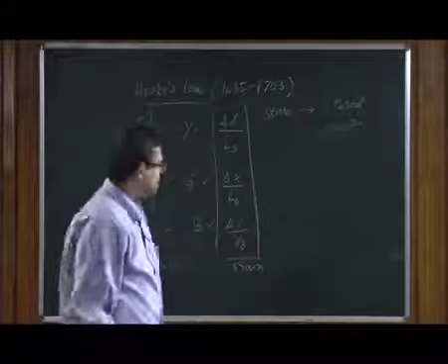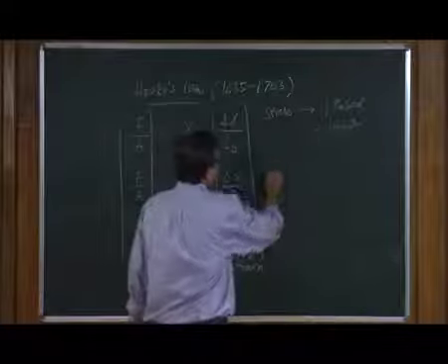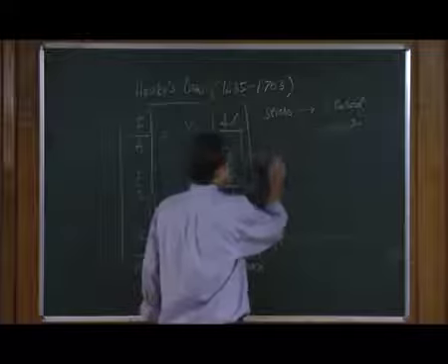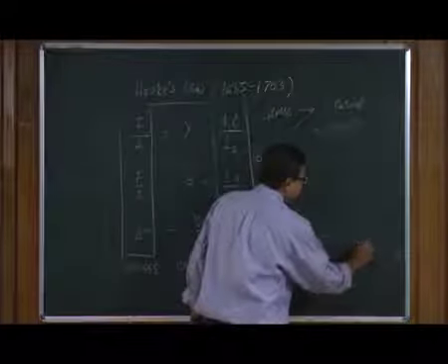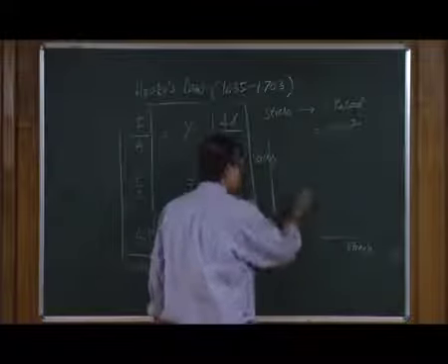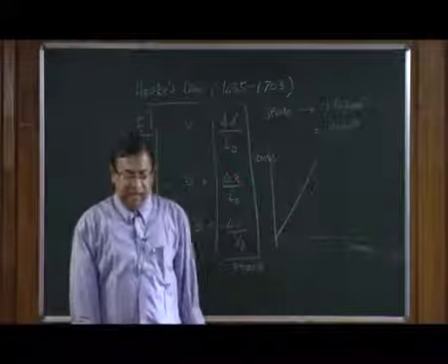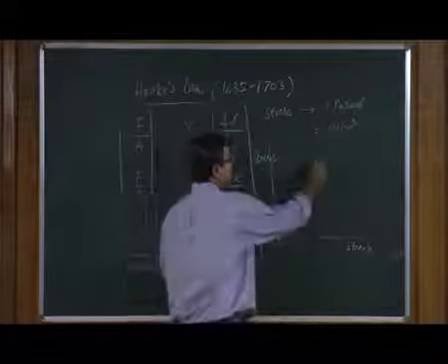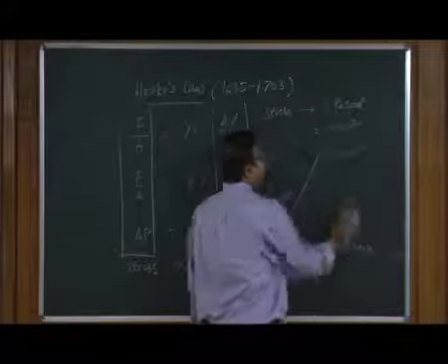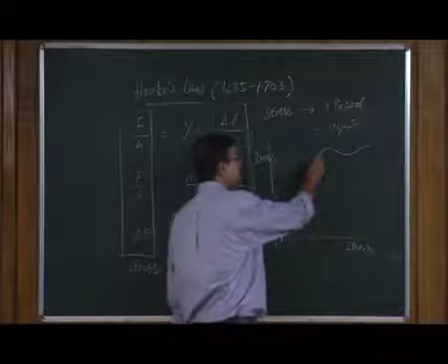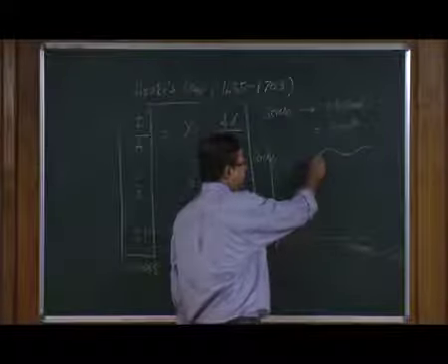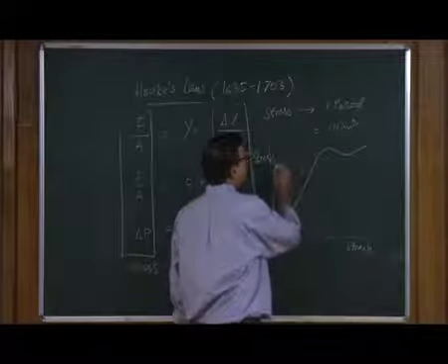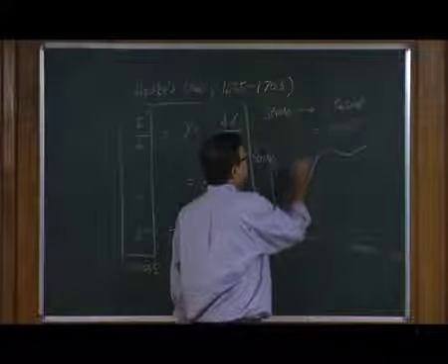And this brings us to the plot where we can plot stress versus strain in a generic manner, and we will get a straight line till certain values of stress, and after that it is going to have a non-linear behavior. The point till which the straight line behavior is obeyed we will term as the elastic limit.